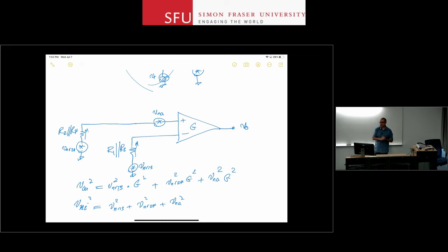Throughout the whole discussion here, we saw that you're talking about power spectral density. Your only way of reducing that noise power is to limit the bandwidth. So the technique that we use here is called synchronous demodulation.